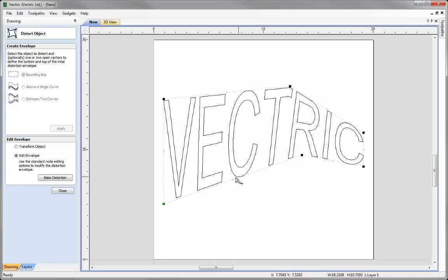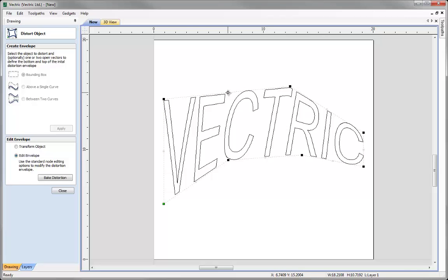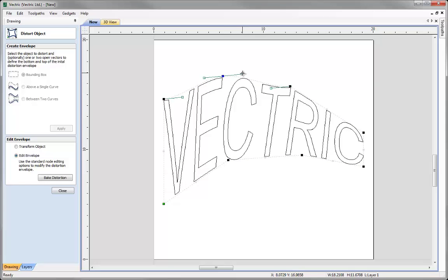Again, we can take advantage of the midpoint, so I could just come over to a midpoint and simply press the letter I on there to change that to a point. So I can jog that up and change this one to a point as well. I may want to smooth this point, so I may want to just insert the point and then select to smooth the point. So I may want to just move that and add some curvature.